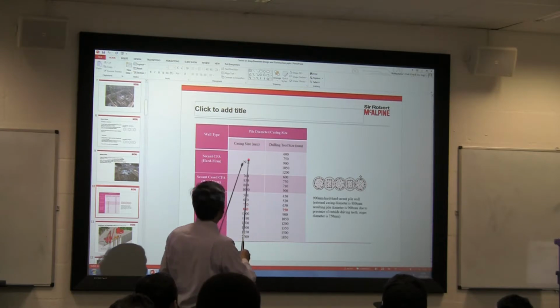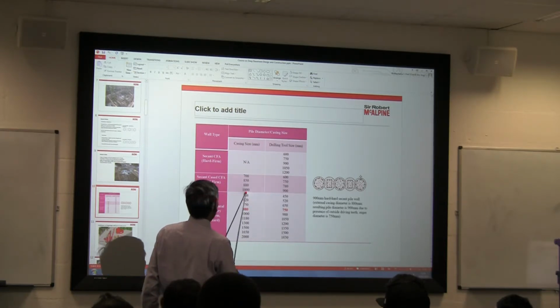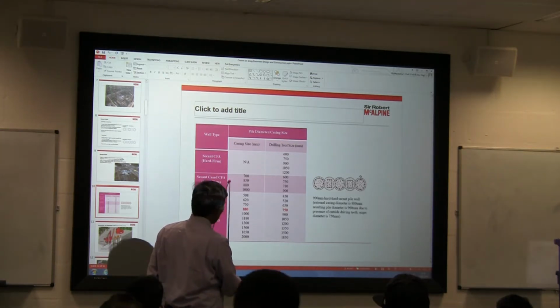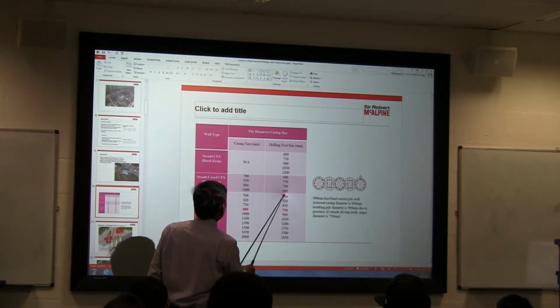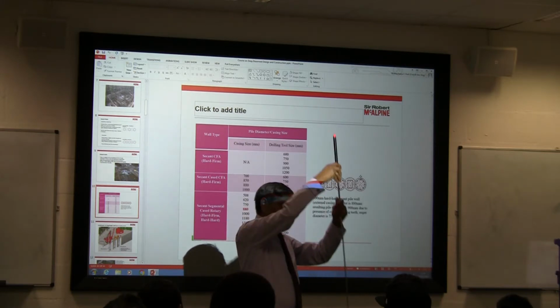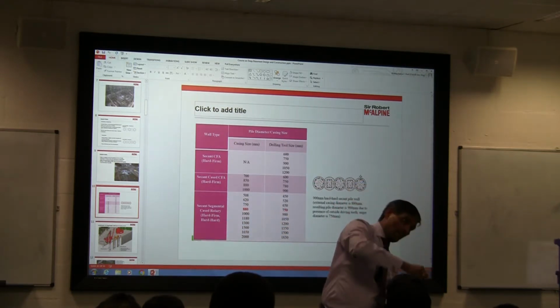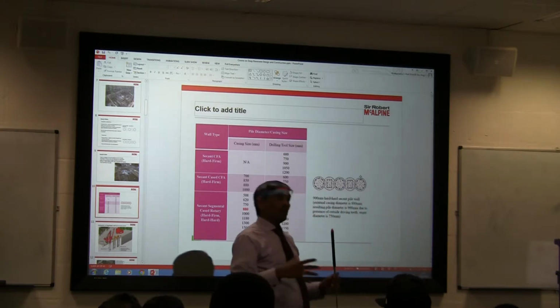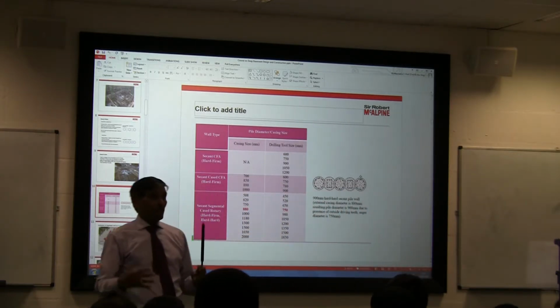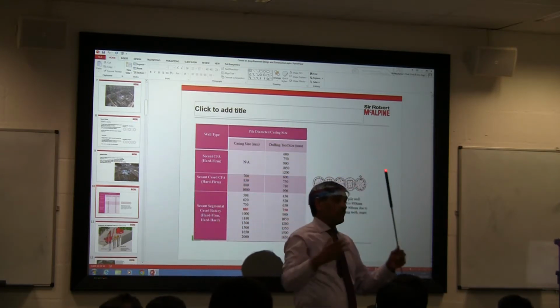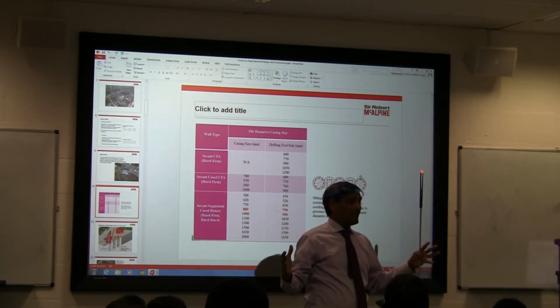Sometimes we put in a temporary casing size. So you can see if you take a diameter of 1000, the casing size is 1000. This is the secant case, CFA, continuous flight auger, and the drilling tool is 900. So you drive a one meter diameter casing, you put an auger in there, and then you drill at 900. So you can see the ground is not collapsing, and when we withdraw the auger, we pour the concrete, and we know definitely a 900 diameter pile is made.